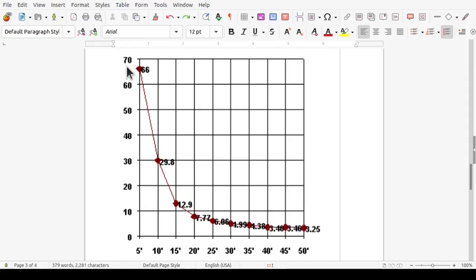We've come down to 1/10 of our value here for 5 foot at only 5 times the length. I'd like to see you pounding in a 25-foot ground rod. This leads us to practicalities. It's rare that you're going to achieve this value, much less this value.